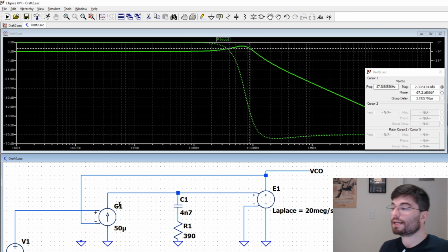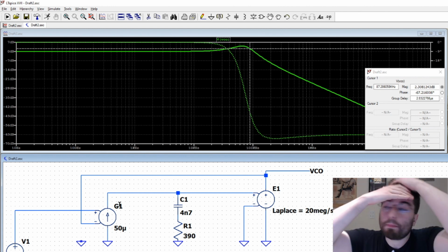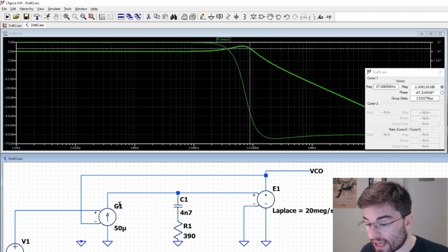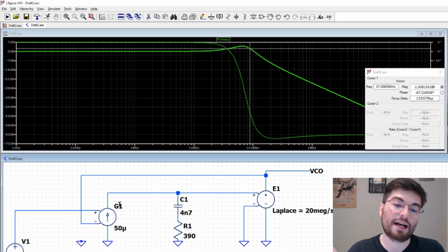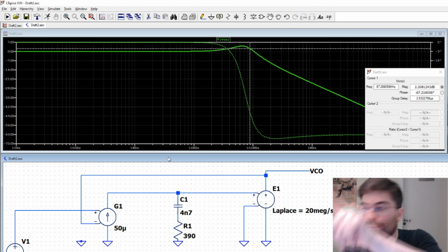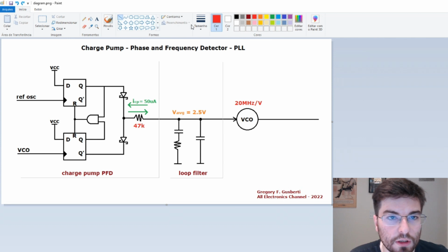Remember, guys, here in our project, we have a sampler, and this sampler is not a divider. This is important. If you have a prescaler, the prescaler is a frequency divider, and the prescaler will look like a divider here. Okay, so we would have an attenuation in the closing path of the PLL. So our PLL, guys, is connected in this way here. This is important. It's important to mention it.